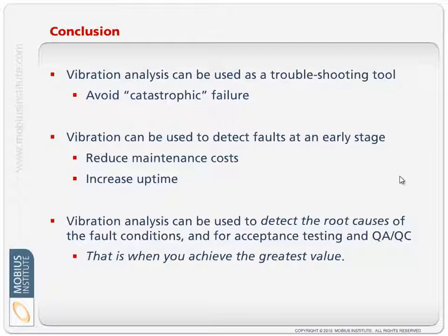But whereas vibration can be used to detect the root causes, we can go even a step further and say, let's use vibration to try and prevent the root causes. Let's be proactive. Let's put a force field around the plant and use vibration analysis for acceptance testing. Let's test that pump and the motor and the fan as it comes into the plant, in agreement with the vendor, and we tell the vendor, if it doesn't pass our vibration test, we're not accepting it.